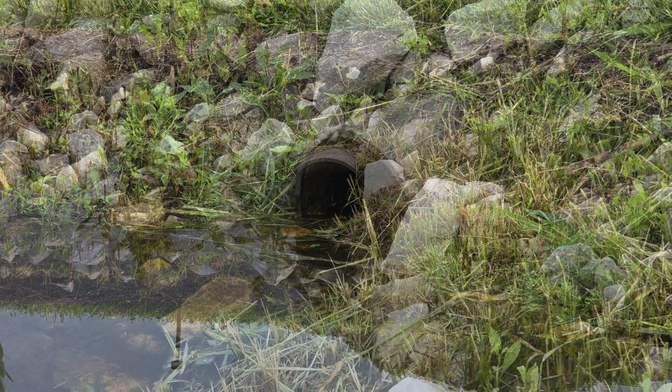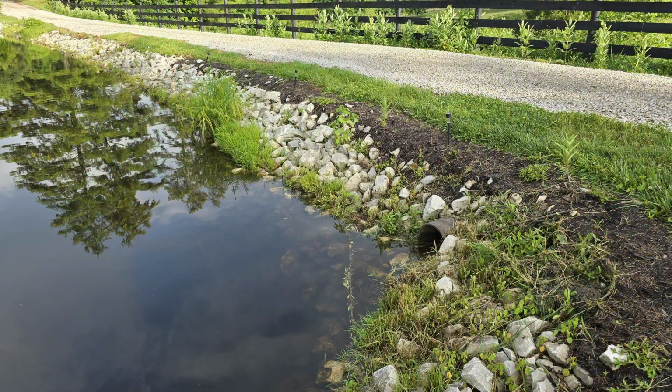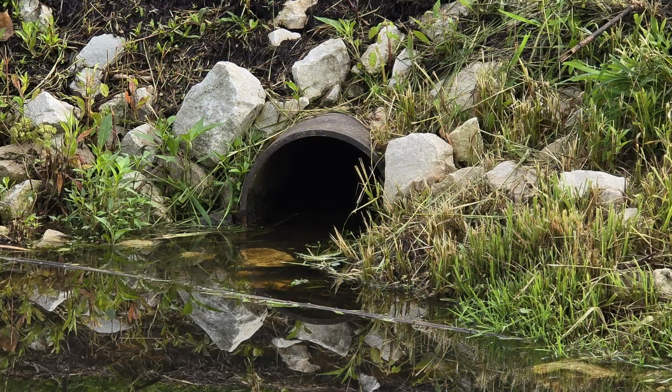A major problem with using an overflow pipe instead of a spillway is that most people install a pipe that is too small in diameter to handle flow during a flood. Large diameter pipes are expensive to purchase, so landowners often think that the pond will last with a smaller diameter pipe. It's of great importance that the entrance to the overflow pipe be cleaned of debris every week to make sure that it stays open.